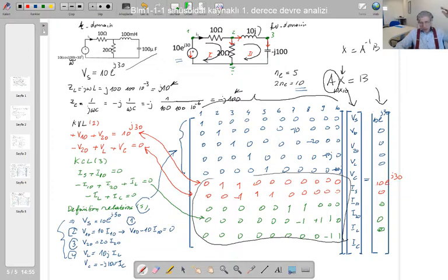So the conclusion that we can get out of this, the first one is this. By this method, you can find all the elements' currents and voltages, but in order to find that, you've got to get the inverse of this A matrix, a 10 times 10 dimension matrix. Not easy to do. On the other hand, you might consider that this A matrix has got many zeros in it. Is there any alternative way of solving fewer equations but still solving the circuit? These are the other methods that we're going to examine. These are the node voltage methods and the mesh current methods.